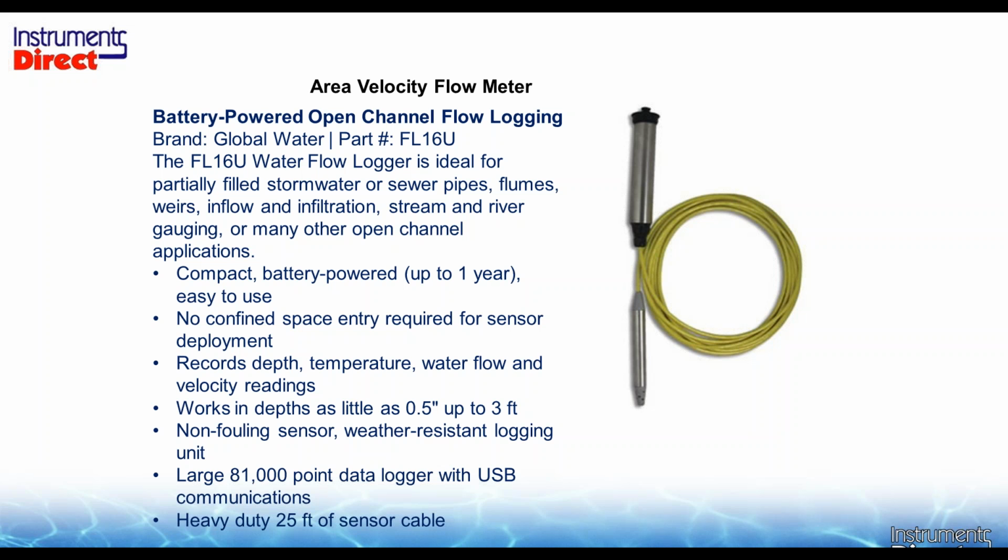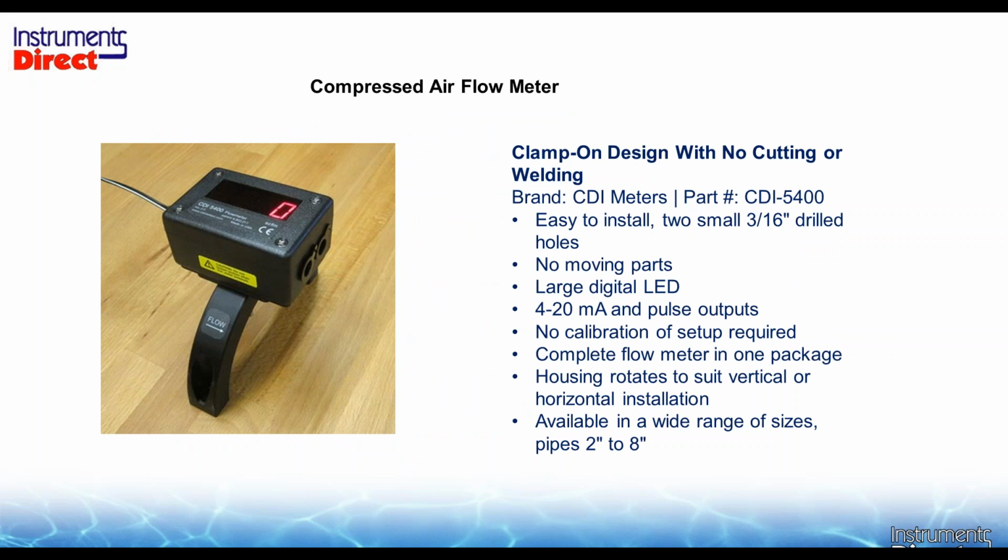In that case, you can put in a flume, you can put in a weir, which both are pretty expensive, or you can use this type of technology, which I believe can go down to a 2-inch line size, and put a dedicated version of the electronics in the application. So there are variations of everything we're looking at here today. This is just a glance at some of the technologies.